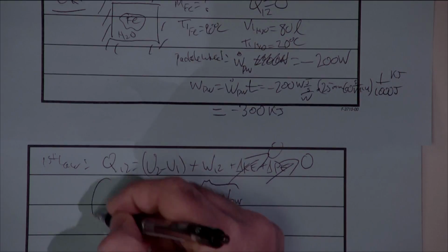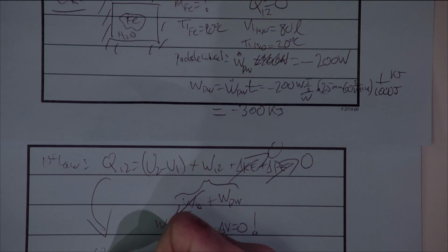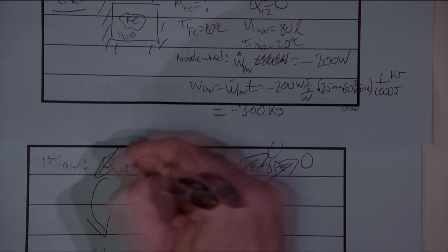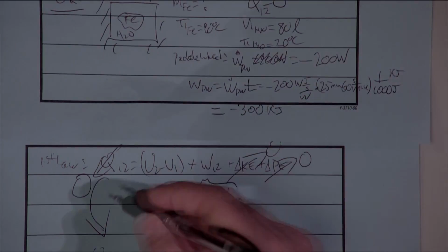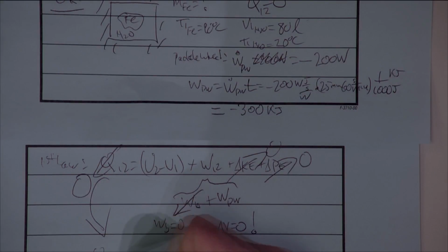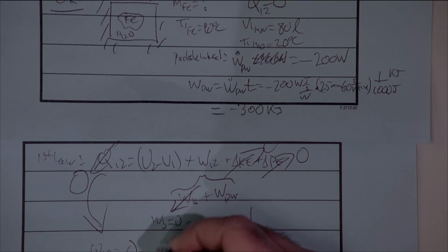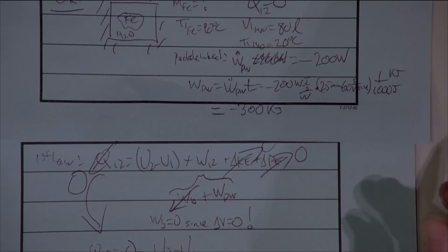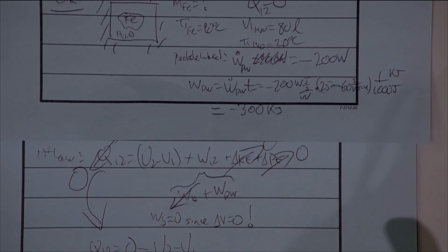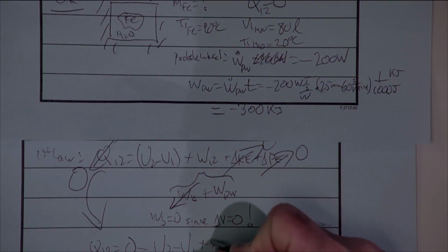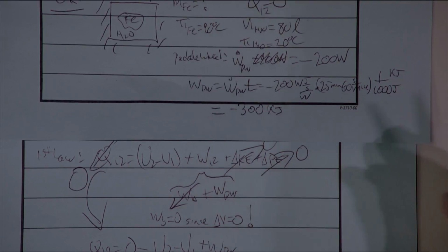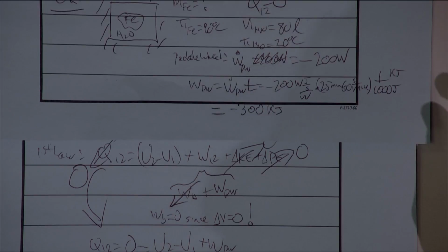So therefore, our first law really just becomes, oh wait, there's no heat transfer either. Even easier. We already stated that. So 0 is equal to the change in internal energy, plus the paddle wheel work. And that's all that's left of our first law of thermodynamics.